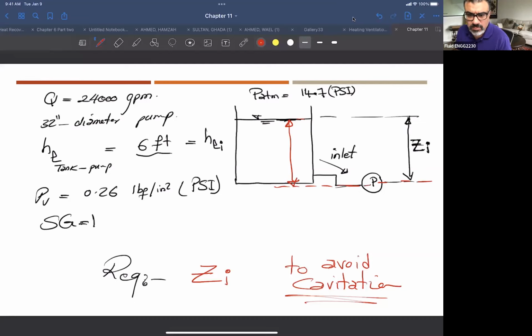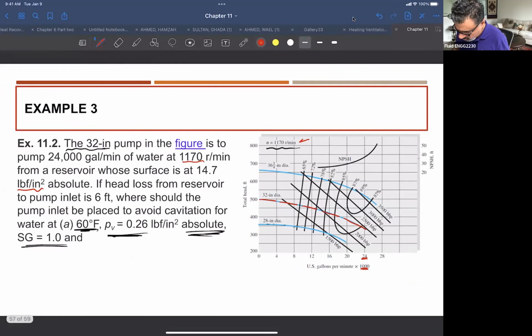And this problem for the pump is cavitation, right? So you don't have to be told to avoid cavitation. It could be a question to you, like, where the pump should be placed. So you decide, in order to avoid cavitation, the pump should be located based on the criteria of net positive suction head, right?